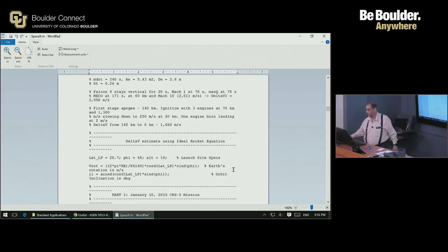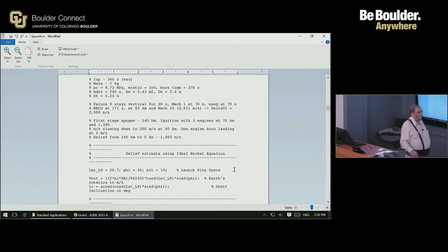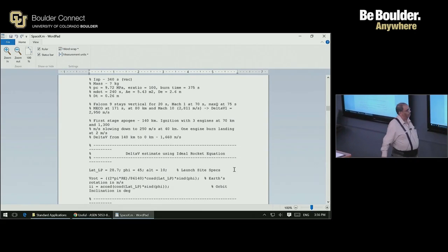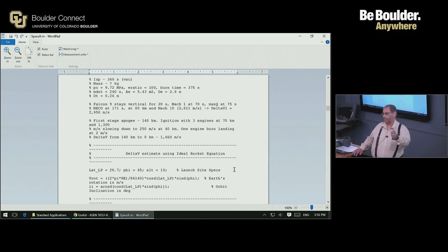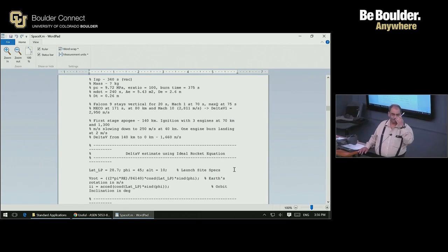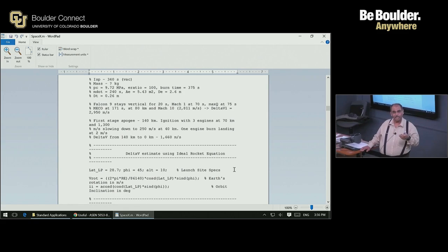And in the first homework, I'm asking you to calculate the overall thrust-to-weight ratio of the launch vehicle on the launch pad. Obviously, that has to be at liftoff. So obviously, that has to be greater than 1 for the vehicle to lift off. Typically, it is about anywhere between 1.25 and 1.5.